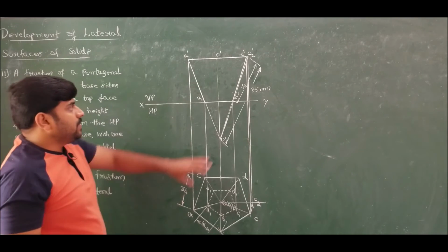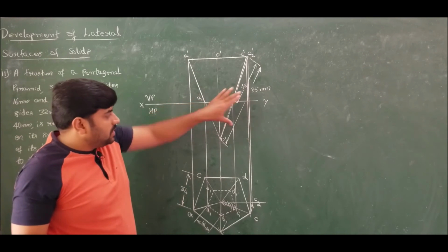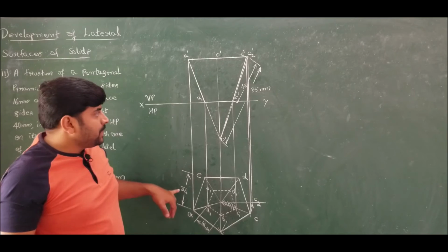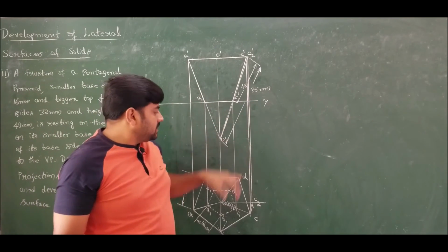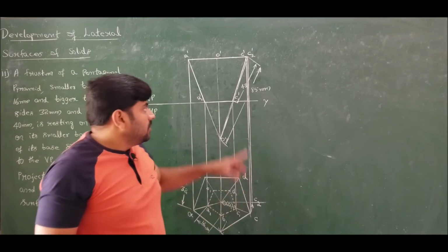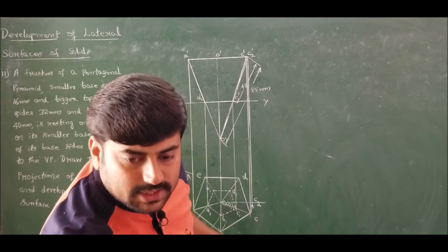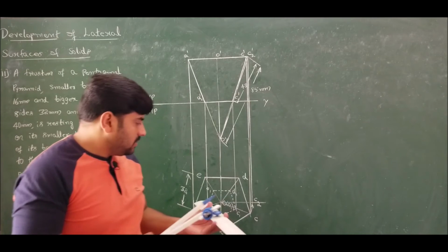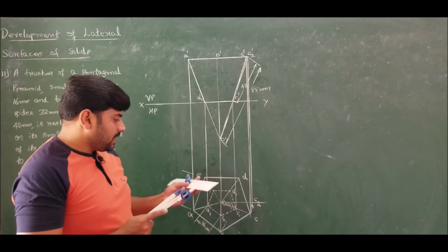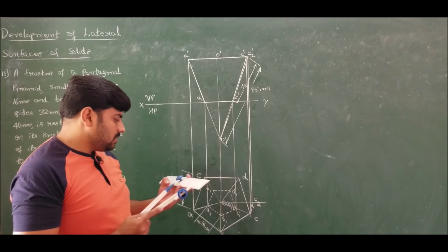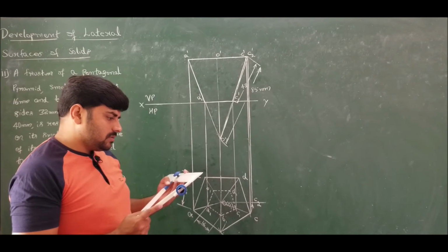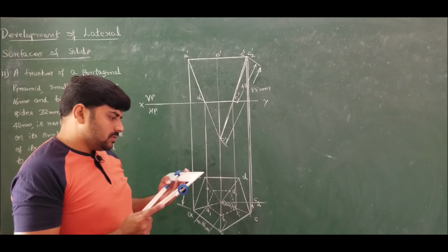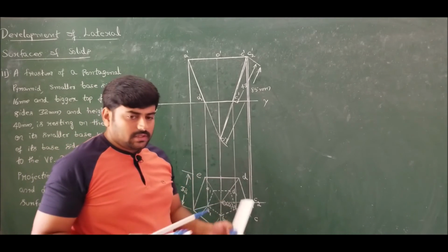Now I can make use of these two slant edges. We know side length as 32. So therefore first you draw an arc for unknown angle, then cut equal arcs at 32 mm side for 85 mm length. That is, if I move for development, first I should take 85 mm dimension. So measure 85. Measured.